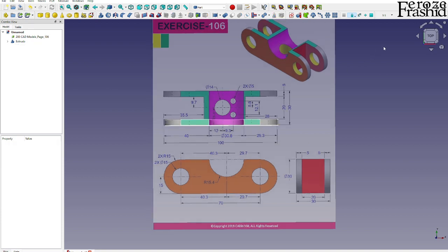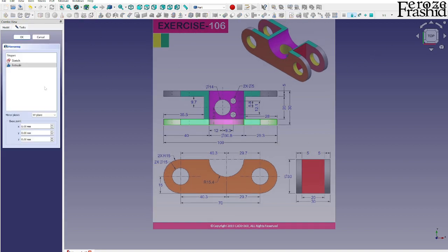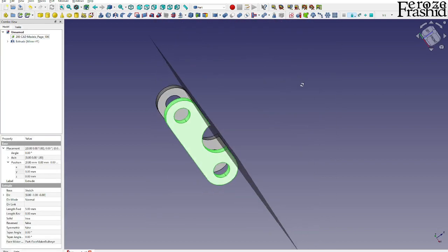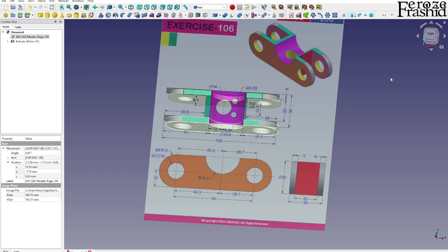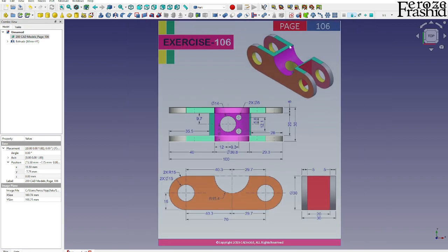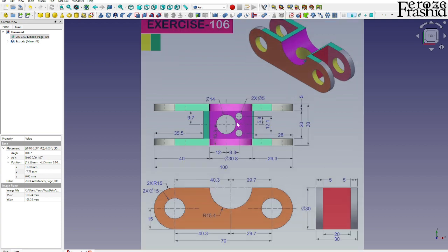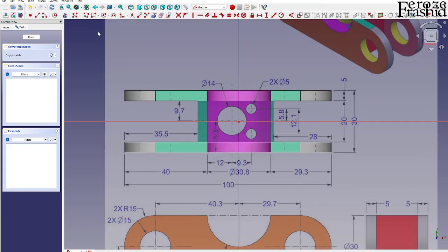All right, now we can make a mirror against the front face, which is the Z plane there, and we get two of our walls built right there. Now let's pay some attention to this middle part, which is a rectangular block, and then there will be 3 holes. I want to build that sketch on the XY plane.